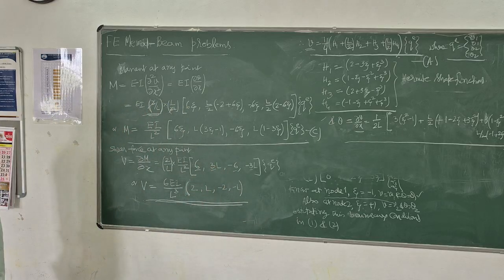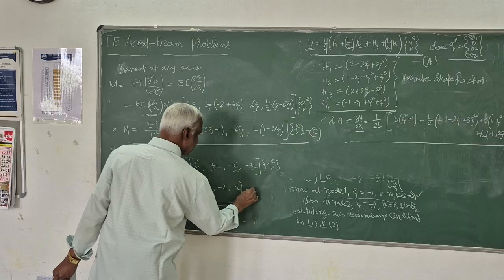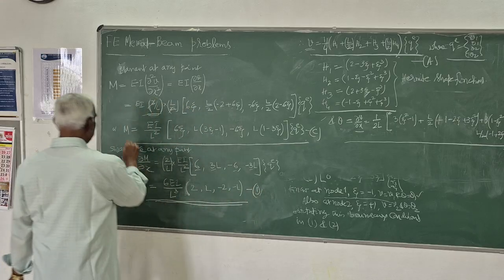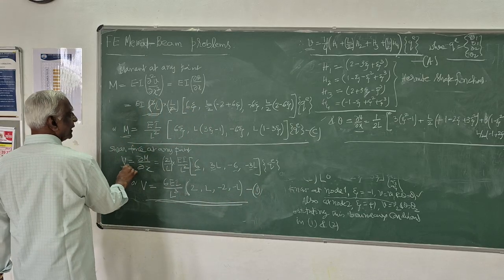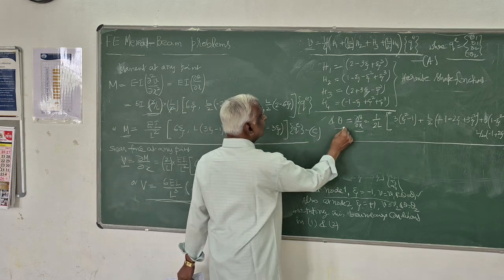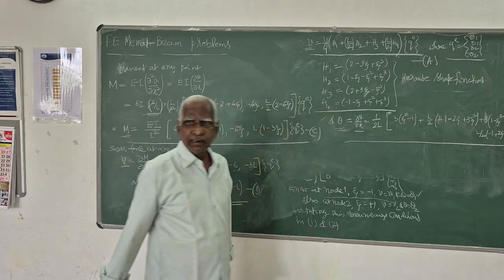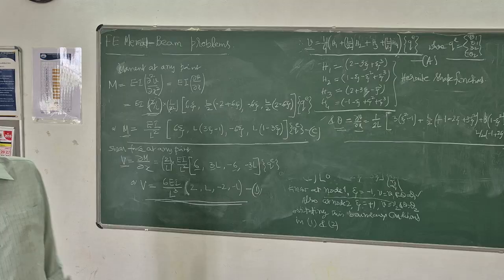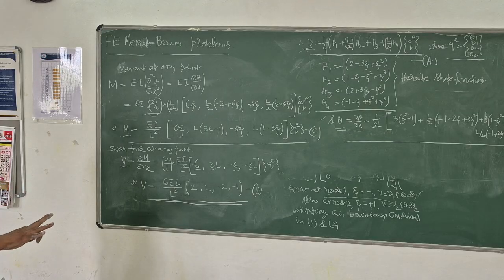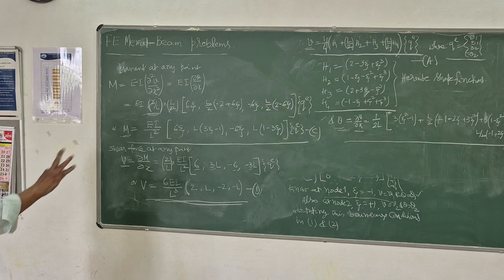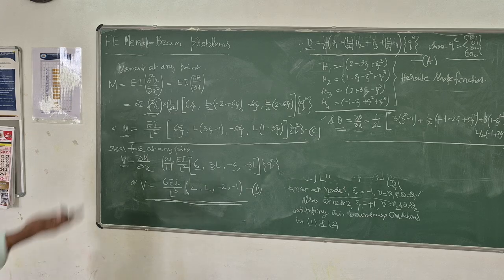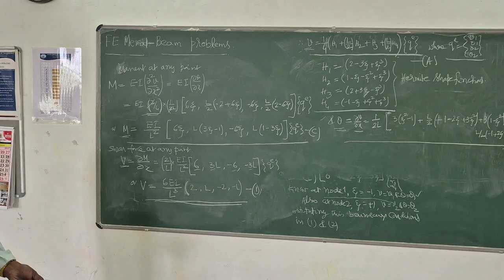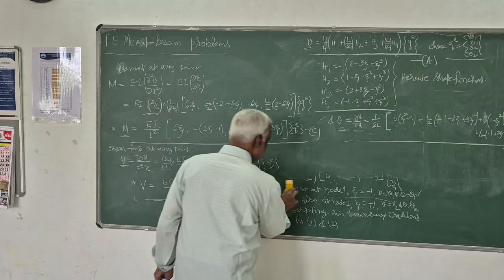This, you call this the equation. So the moment equation, the shear equation, the slope equation, and the deflection equation at any point. If you remember this, and also the derivation as well as the expression, you can derive the stiffness matrix for the beam element. So that we will take up next.